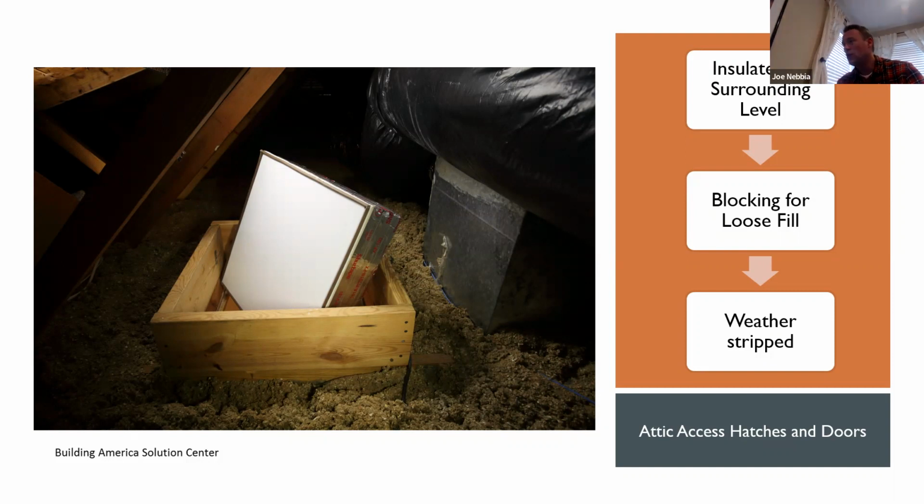And you still could use a UA or something like that, a whole building U value comparison, if you're willing to go to that detail. I think this is an area where there's quite a bit of non-compliance with the code. I very rarely see these hatches insulated to R49 or something like that. It's usually much less, but that's what the code says.